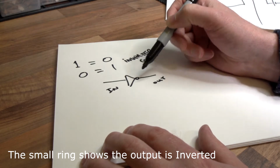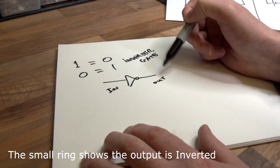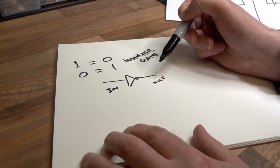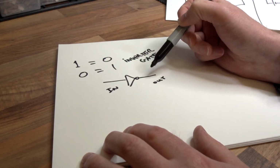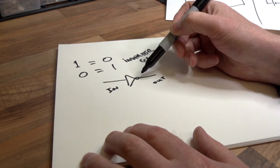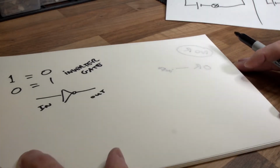If it doesn't have the ring, this would actually be what they call a buffer, where the signal would just be the same all the way through, and all it's really doing is doing a current transformation. It's working like an amplifier, really. Small signal currents to big currents, that sort of thing. But there wouldn't be any logic change. You know, a 1 in would still be a 1 out. But because we've got this little circle on the output, it means inverted. It's an inverter gate.